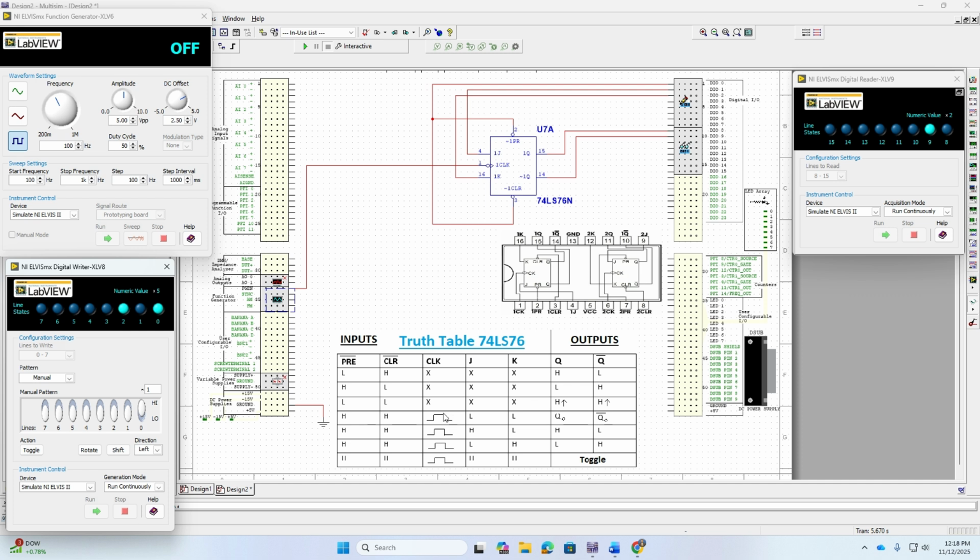And again, there's our simulated clock pulse, just a little bit of picture. What it's saying up here is that when you have these set, the high and low, the clock doesn't matter. Neither does the JK matter, because it's the pre and the clear that's actually setting the output. We're just going to look at the operation of the JK. So we have a clock, and the clock is just to show us when this thing is going to transition, and ours is negative edge, so it's going to be transferring from high to low. We've already set this hardwired to high. All we're going to do now is adjust the J and the K inputs, and we want to make sure that they actually match the outputs of the predicted operation of this JK flip-flop.